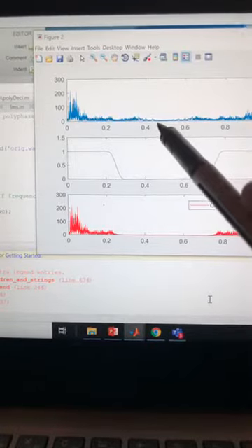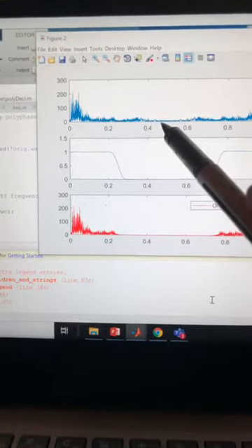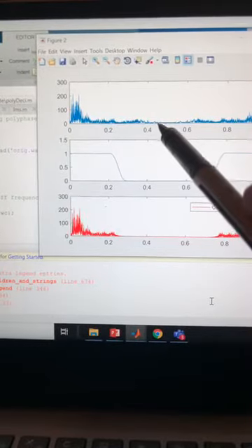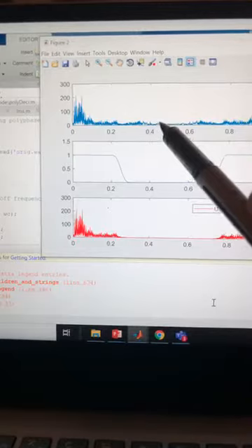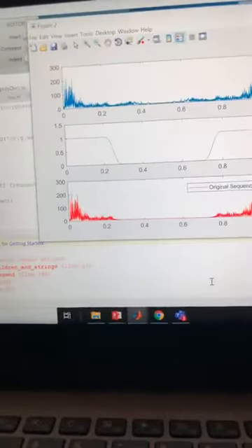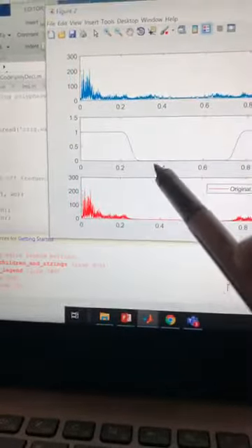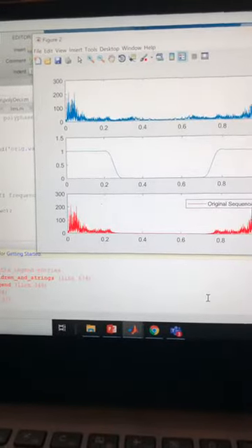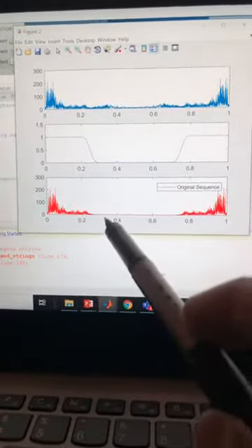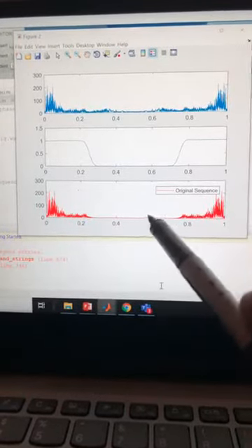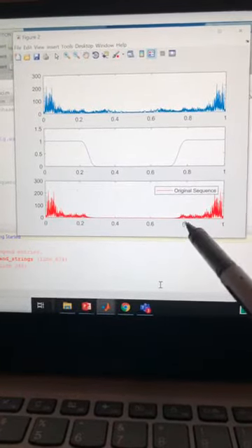So instead of sampling it at 11 kilohertz, you may decide to sample it at 5 kilohertz. Or you already have this voice, okay? This is a copy of the spectrum at 0 and 2 pi. And you say, I'll pass it through a pi by 2 filter, and I'll throw away this part of the spectrum. You see this? This is the first operation.